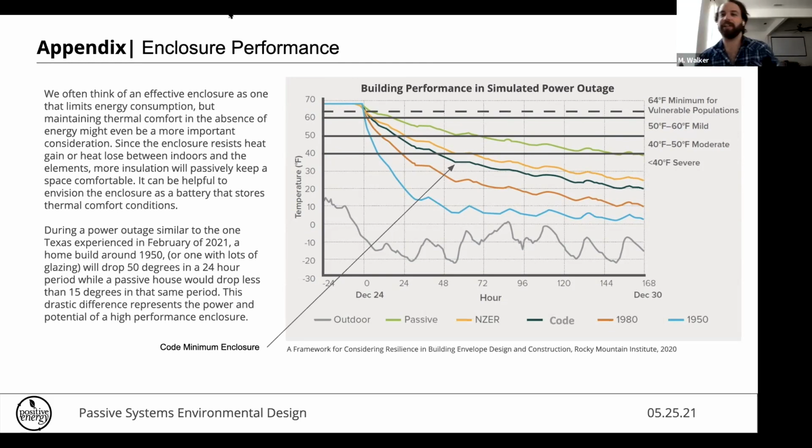Let's assume good daylighting. That's a Corey question right there. You'll have to get Corey to answer that. But just going with default floor to ceiling windows in all the rooms, a window is a terrible wall from an insulation standpoint, and it also lets through heat in the form of visible and infrared rays. So even high performance passive house glass is still a marginal wall compared to a code minimum wall. So being strategic about that will increase the benefit.